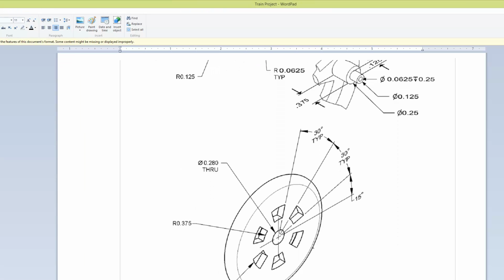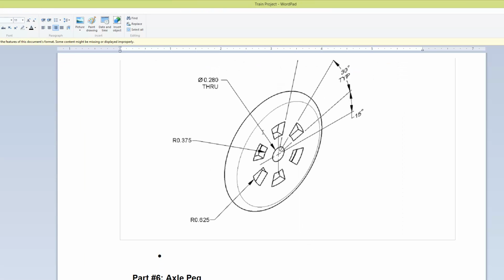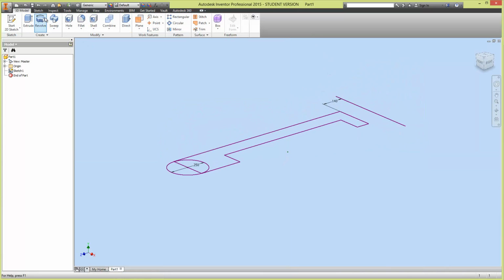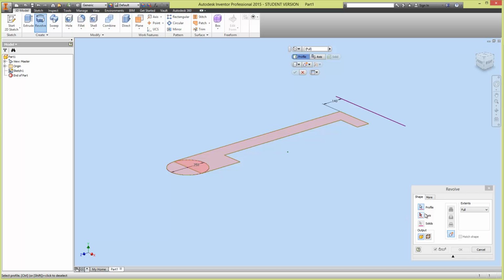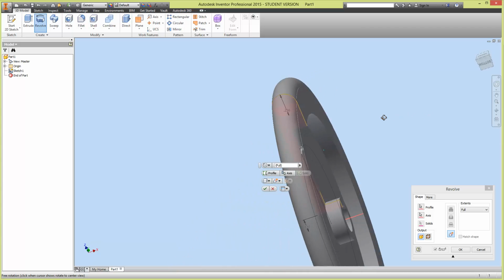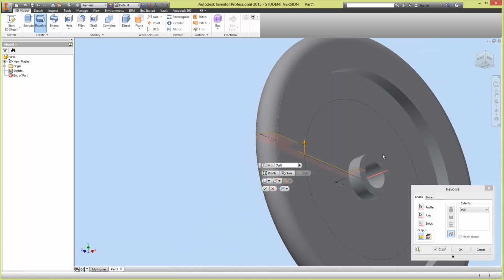And looking at the bottom photo, I can tell that this opening down here has a diameter of 0.28, so if I was going to dimension it to the bottom of the part, I would probably dimension this 0.14 because that's half of 0.28, so that eventually when I'm done with this sketch and I've dimensioned everything for my axes in the revolve tool, if I clicked on that, it would revolve and it would generate the wheel. So that's kind of how you want to approach it.